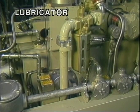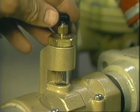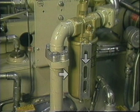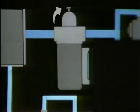An inline lubricator supplies atomized oil to the starter motor vanes. The lubricator includes an adjustable flow valve, a 2-quart capacity tank, and a sight gauge. Looking at this cross-sectional view, we see the lubricator's internal operation. As the main supply gas enters the unit, a portion flows downward, pressurizing the oil in the bowl. This pressurization forces oil up the center tube to be delivered to the main gas flow. The delivery rate is set to 60 drops per minute by an adjustment knob at the top.